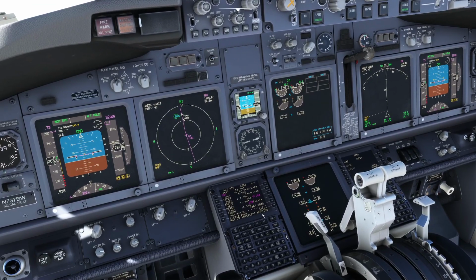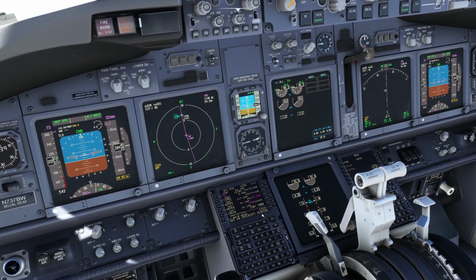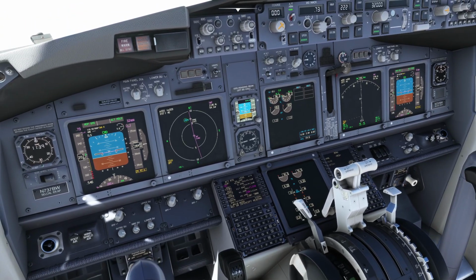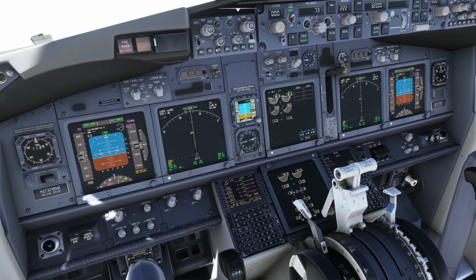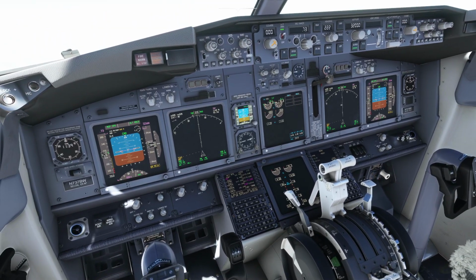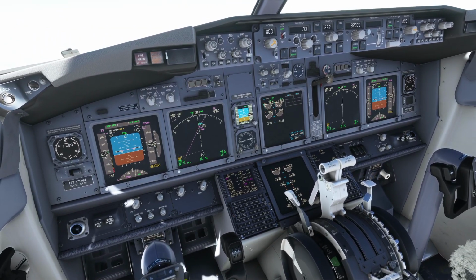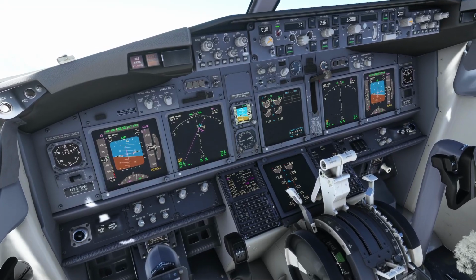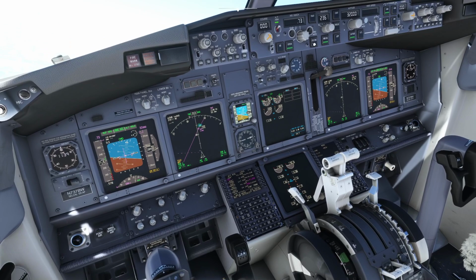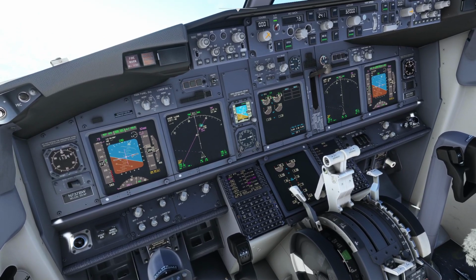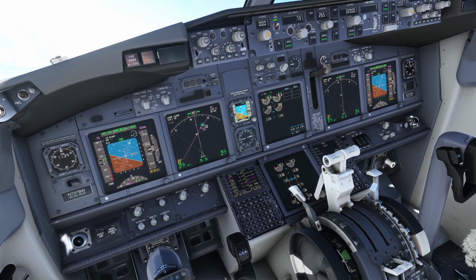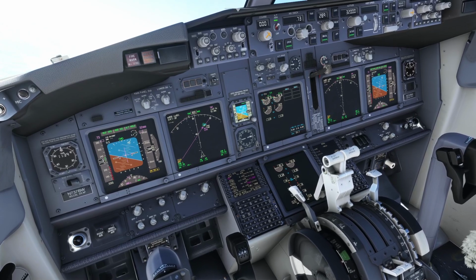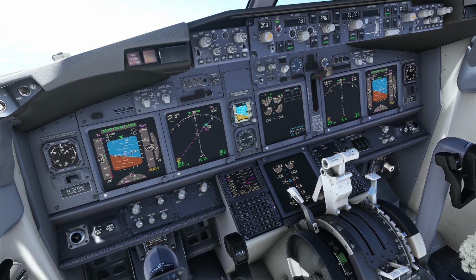See, look, now we are not on an intercept heading. Okay? Which makes perfect sense. If we zoom out and show this, and zoom out further, yeah, we're not on an intercept heading for that course, so we need to enter heading select mode, and we need to tell the aircraft to go on to an intercept heading for us. So it's not going to perform wonders. So we're just changing our heading for heading select mode, which is fine.